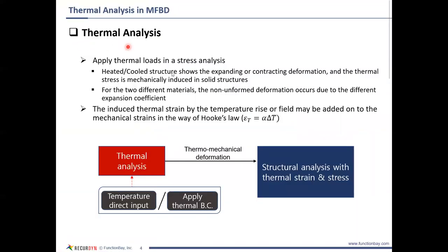Okay, so to start off with, we now have thermal loads as an option within FFlex. So what you can do is apply boundary conditions, thermal boundary conditions, to a FFlex body, and then that conduction will transmit through the material, and you end up with thermal strains that occur because of that. And we'll look at some graphical representations of that. But basically what happens is you'll see the material begin to expand or contract based on the conduction happening within the material.